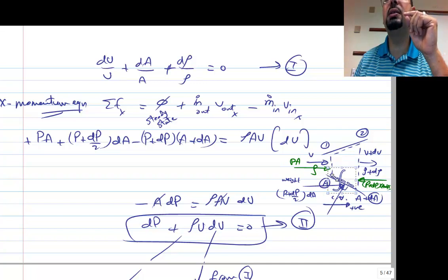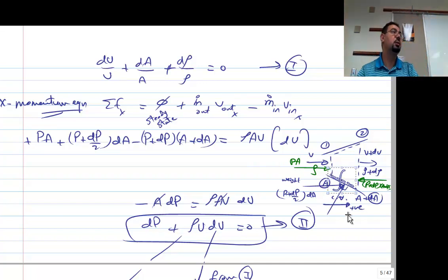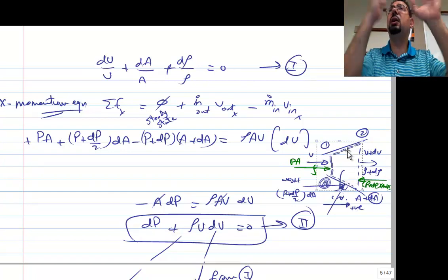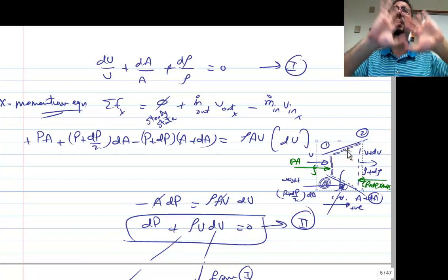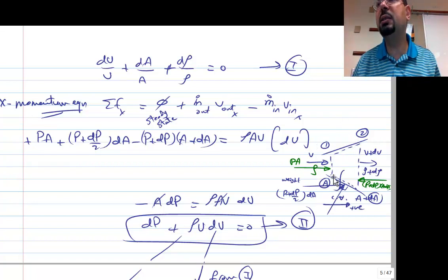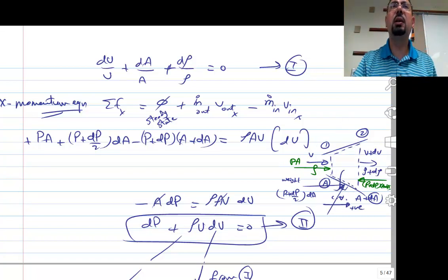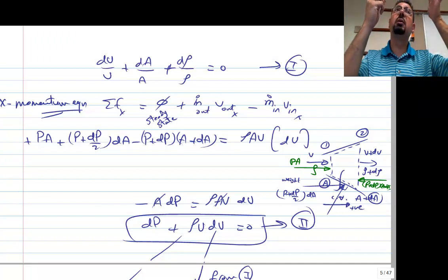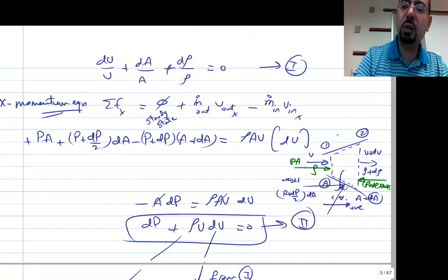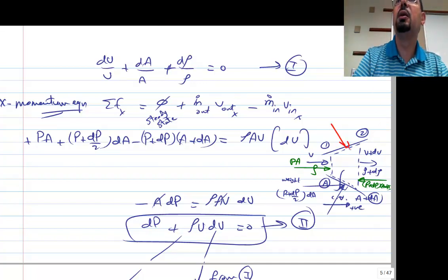Right. So look at this. This surface also has pressure force on it, right? What is that? That's the cone, that's the conical wall area. This is a nozzle expanding. It's axisymmetric, so that surface has pressure on it. Which direction should the pressure be? We always said the pressure should be normal to the area. Excellent. So we should have put the pressure like this, multiplied by this area.